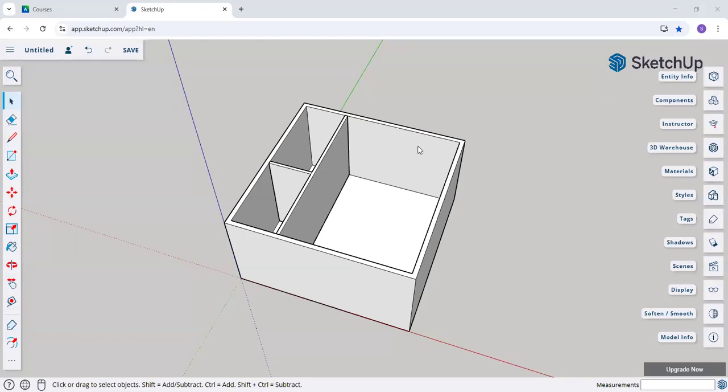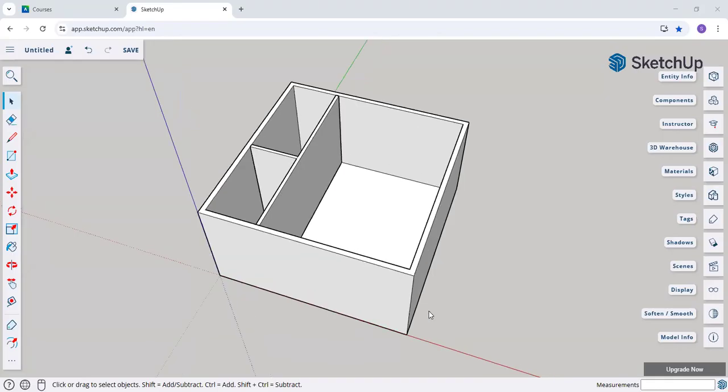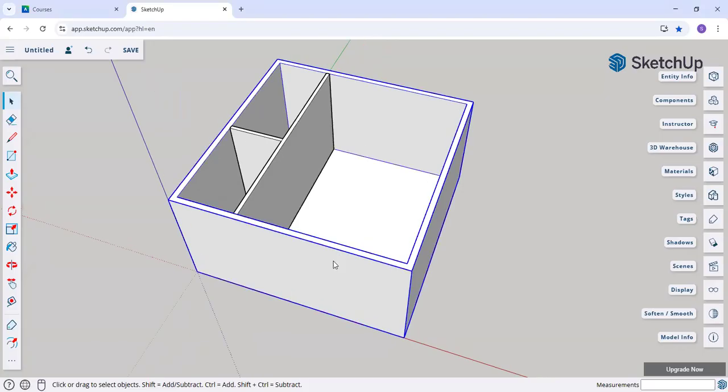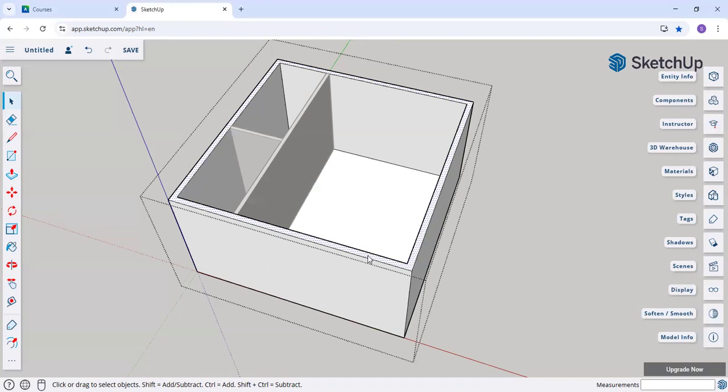Welcome again. In this tutorial, we'll talk about how we're going to create some doors and windows. Right now, we have two groups, if you remember: the exterior walls and the interior walls. If you want to do any editing or updating, you have to click on the group two times to open it up, so you can edit the walls, make cuts, or move any changes. You cannot just do it when it's not active in view.